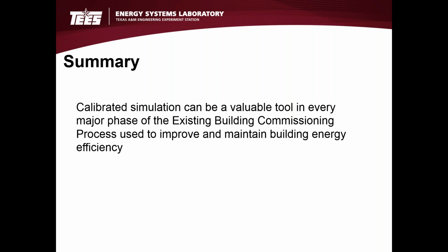Okay, when we look at the modification parameters, we are going to look at them on the basis of what systems are in the building and what parameters we know tend to have the most impact in changing consumption in those buildings. In the calibration process, fundamentally we have programmed a number of changes. Certainly if a building has a constant volume system, it will look at a different set of modifications than if a building has a variable volume system. And if it has district cooling, it will not look at chiller measures and things like that.